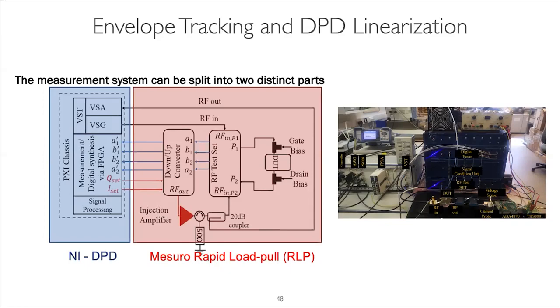So it's what they call the VST, and it basically has both the signal generation and the analysis, but also we have a real-time FPGA in there. So the real-time FPGA is linked directly to our down converter and up converter. As you saw if you look at the quasi-loop architecture, this is what we call the quasi-loop, where you basically use the RF signal down converted and send it to the FPGA, and we do some math on it,